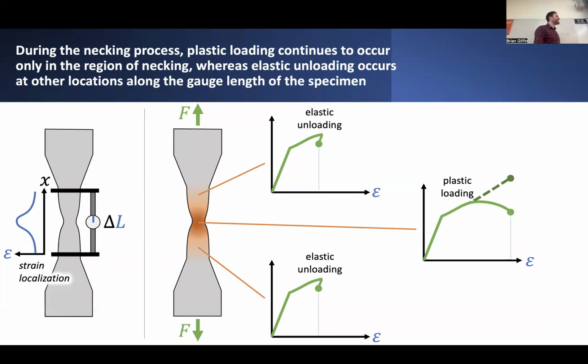And we'll dive into that subject in the next lecture as we start to move away from material nonlinearity and instead discuss geometric nonlinearities. As we'll see, necking behavior is something of a combination of both material nonlinearity and geometric nonlinearity happening at the same time. You can see why this is a geometrically nonlinear phenomenon by virtue of the fact that we had to normalize this measure of stress by the actual deformed area of the specimen. So we had to take those deformed geometric features into account when we define what we mean by stress and what we mean by strain.